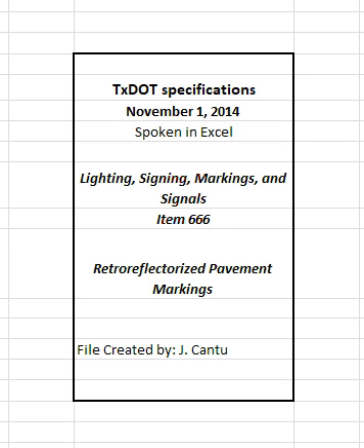In addition, at a longitudinal spacing indicated on the plans, the markings must be profiled in a vertical manner such that the profile is transverse to the longitudinal marking direction. The profile must not be less than 0.30 inches, 300 mil, nor greater than 0.50 inches, 500 mil, in height when measured above the normal top surface plane of the roadway.